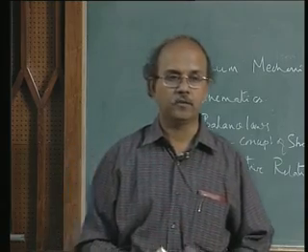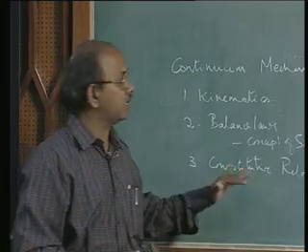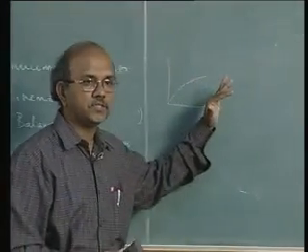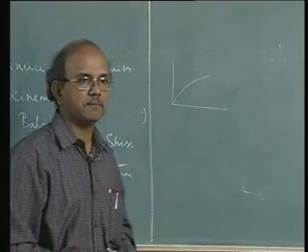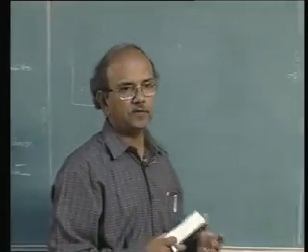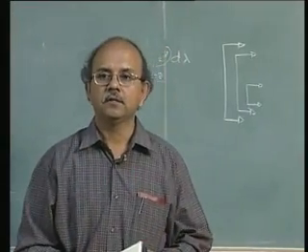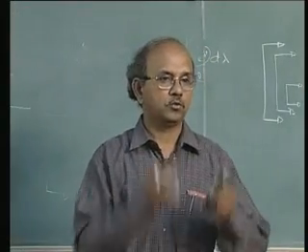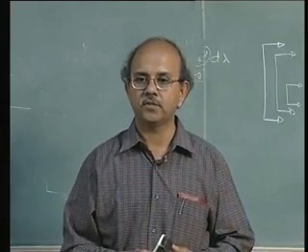So it's very important that you realize right now that constitutive relations are not just a curve fitting between stress and strain. Why I'm stating this is because many of the packages deal with constitutive relationships in two ways. One is to ask you to give two columns where you say this is the strain and that is the corresponding stress.